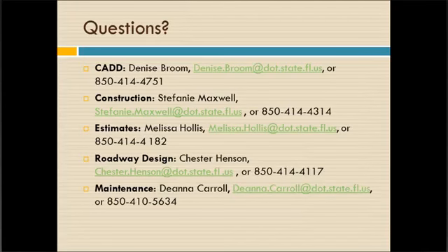This is where a lot of times when you get into concrete pavement, especially on 2-lane, the audible vibratory overrides the edge line material. So on a center line where you would normally have permanent tape on a concrete pavement, if it's 2-lane, you would now have a profile thermoplastic on the center line. But that's over 50 miles an hour. If it's less than 50, yes, you would still have the tape for the center line. The lane lines. What goes on the lane?